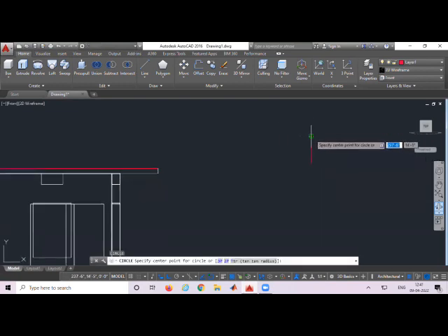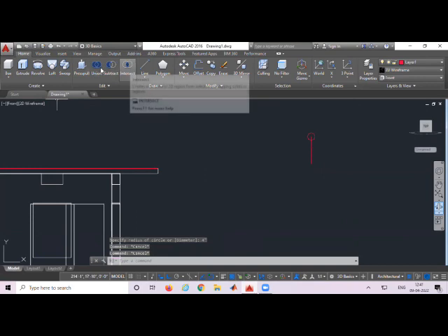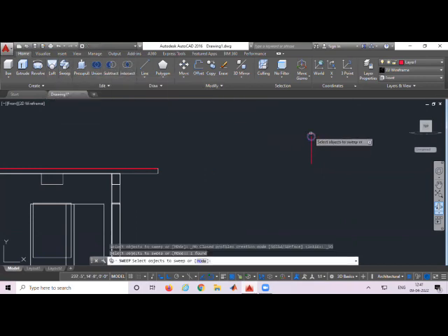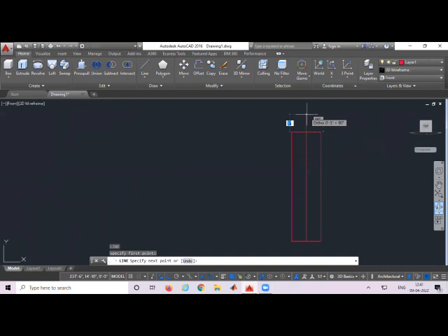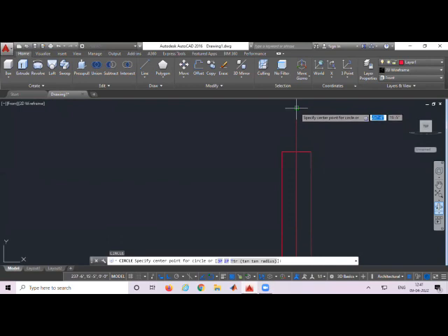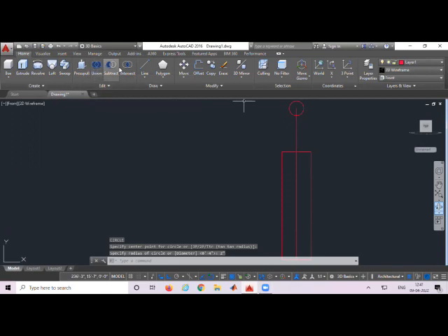The reason I mention this height is that I have converted the total object into the front view, as you can see. Next, circle. The circle has been created at the center, with reference to the center, and provided with 4 inches. Next, sweep. Select the sweep, select the circle and select the path, so that it is converted into a circular cylinder. Next, L enter, 1 feet enter, so that the total height becomes 2.5 plus 1 feet, 3.5 feet.